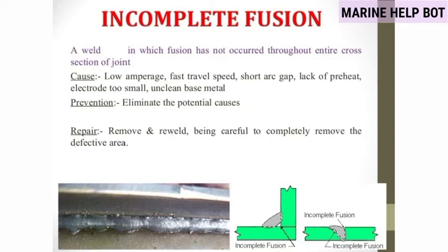So cleaning is very important while welding. If we are not cleaning, it may lead to many defects. Like slag inclusion is also due to not cleaning the welding joints, and incomplete fusion is also due to not cleaning the joint properly. So friends, in this video I will cover the key points which will make you understand all the defects, because if I go slow, this video will be very long.